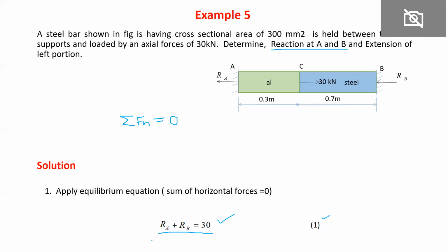As we already learned in the introductory lecture, there are different kinds of equations: the first is the equilibrium equation, the second is the constitutive equation, and the third is the compatibility equation. The constitutive equation is used to predict the behavior of the material, and the compatibility equation shows the conditions under which the entire frame works.